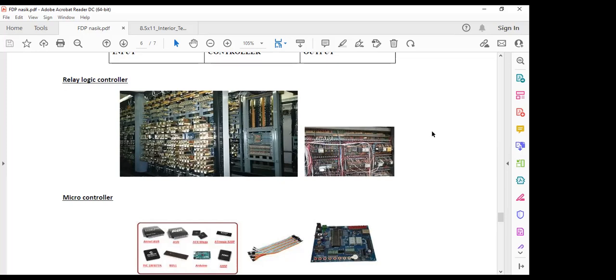But it has a spring system. As you leave the push button, what will happen? The push button is off, you can say, correct? Once more, the push button has a spring system. When you press the push button, it will give you continuity. But as you leave it, the push button is off, which means you are not getting supply through the push button anymore.